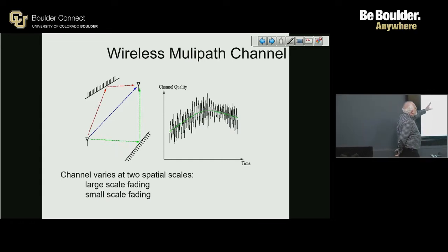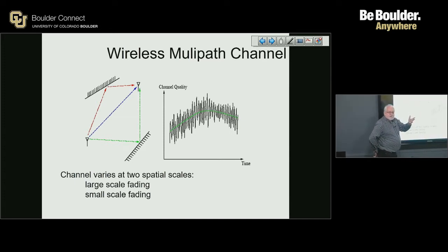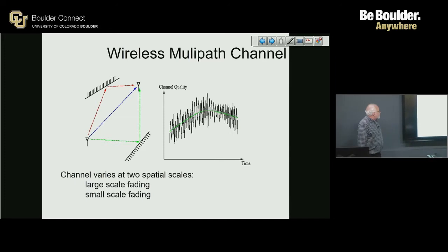So you can imagine that this gets to be fairly complicated, right? Because any environment like this is a very complicated environment for electromagnetic wave scattering. And so you'll end up with a direct path. You'll end up with what is called a two-reflector or 2-path reflector. This is a very simple example, but even with this, if these are moving relative to each other, you can have some significant fades in and out as devices move through, even in a 2-reflector model.